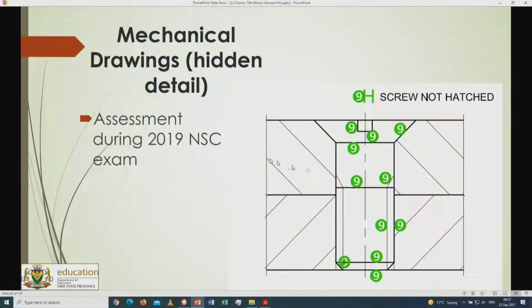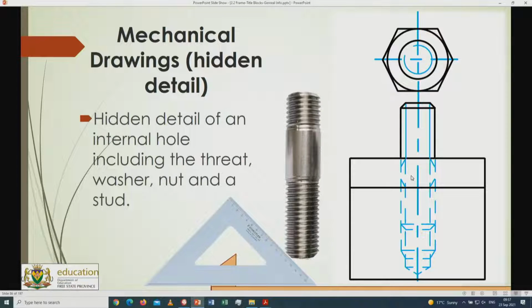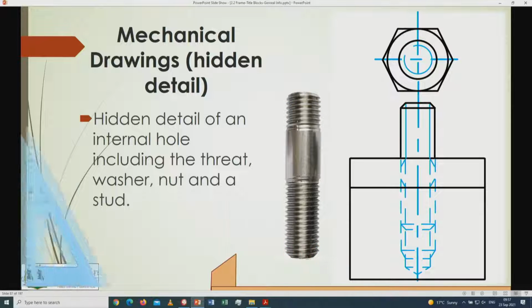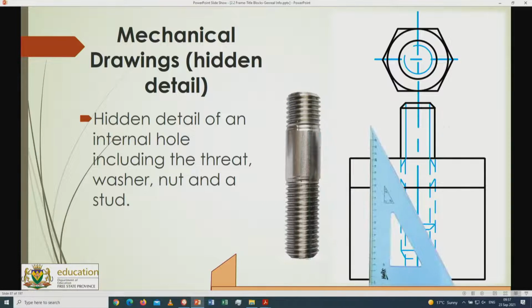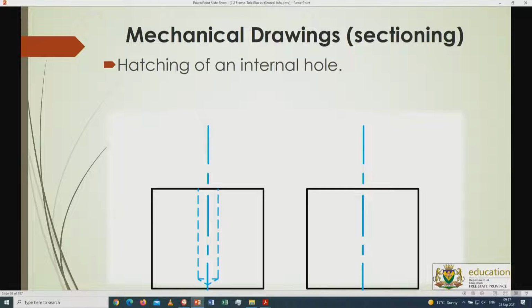Now, this is coming from 2019. This is the question paper I've pointed out to you. Can you see how many marks of this, of what I've explained to you just now? The 45 degrees, the 60 degrees over there, the solid line type on that side over there, and then, of course, the rest of the head of the screw itself. That is 45 degrees edged off, we said just now. And then from there on, that is 60 degrees for studs or for bolts, it doesn't matter.